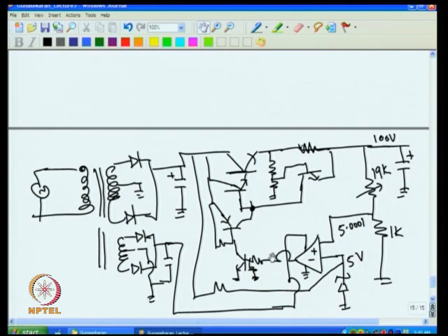So essentially, if this voltage increases, then you will have increased current through this, because the base current is increasing, and that will increase the collector current here. That collector current eventually comes from here. So you will have more current flowing here, producing more voltage drop. If the voltage across this goes above 0.6, then you will have more voltage at this point. So an increase in voltage increases this voltage and that voltage at this point. That increases here, and then that increases this and further increases this. So it will go into positive feedback.